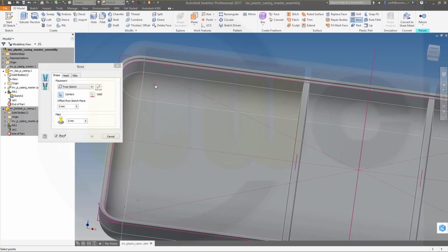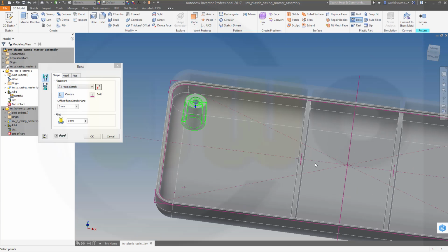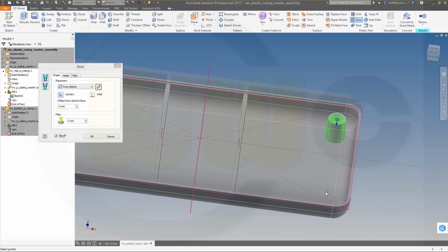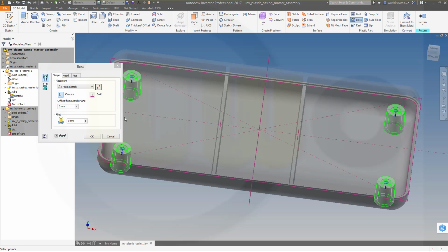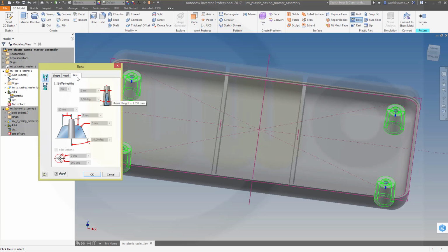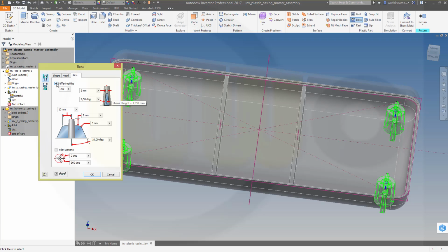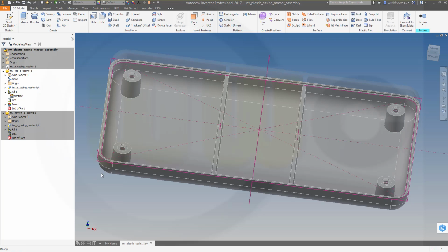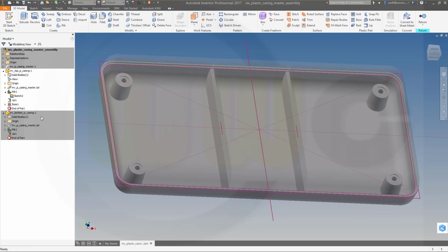That would be that sketch, so I got these points for the dome. You could change all the values. You could add the master draft angle if you want, and you could do it with ribs as well. Very, very convenient. But I will go for these. Confirm.